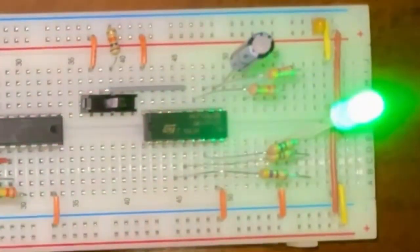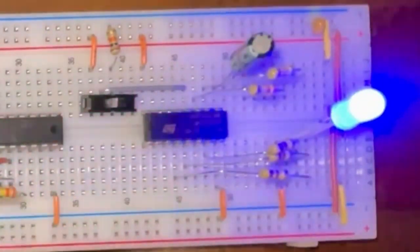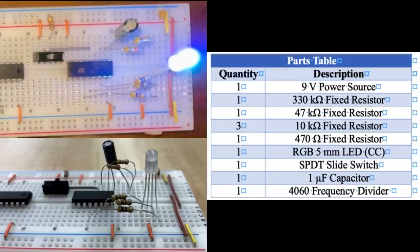The 4060 frequency divider counter is the second circuit. This circuit consists of 7 parts: one 9-volt power source, 330k ohm fixed resistor, 47k ohm fixed resistor, 10k ohm fixed resistor, 3 470 ohm fixed resistors, 1 RGB 5mm LED, single pole double throw slide switch, 1 microfarad capacitor, and a 4060 frequency divider chip.